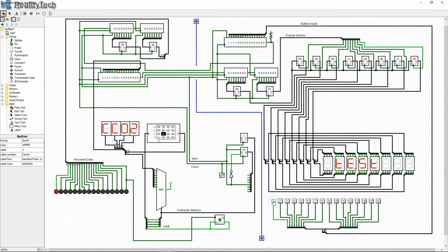Again, if I press a button, you'll see that shift in, or you won't because it's not quick enough. But you can see there in that latch, if I hit this, you'll see that changing. And then all we're doing is again using the synchronization pulse to latch the data in, and then down a bus into there, and the LEDs reflect everything. Now what we're doing with the shift key here, if I press that, you'll see we go to shift.